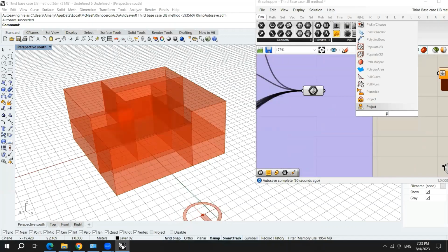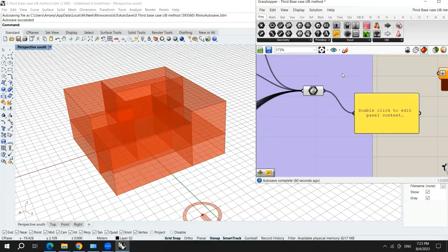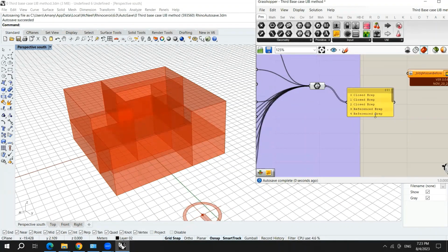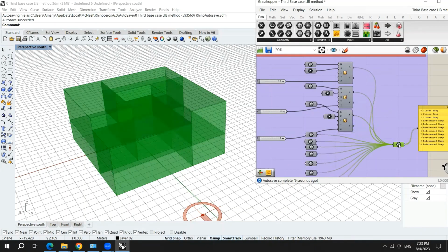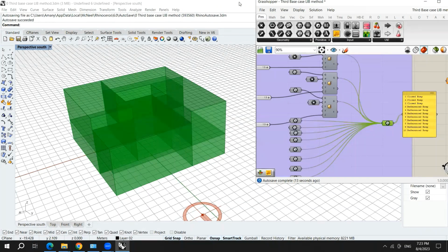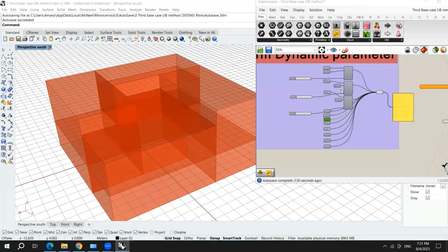So we will check to make sure we have 10 zones here. So we have 11. So there is a problem where in this component we have hooked up something more than one time. Or maybe we have assigned 2 breps for just one box. And this is a very important point. You need to check step by step that you're modeling your building in a good way, because you cannot fix these problems later on.